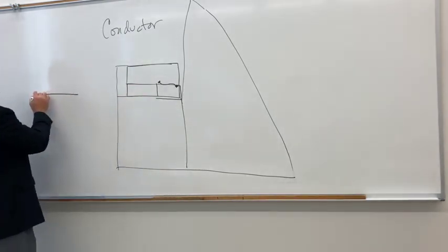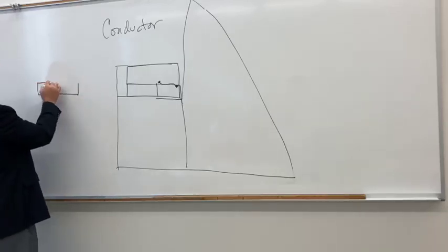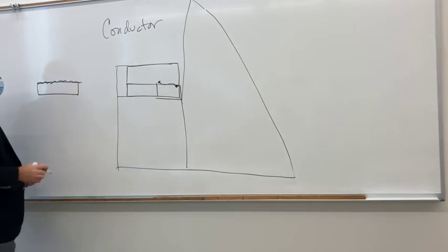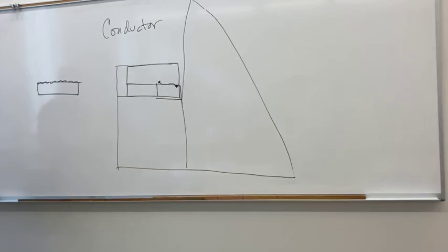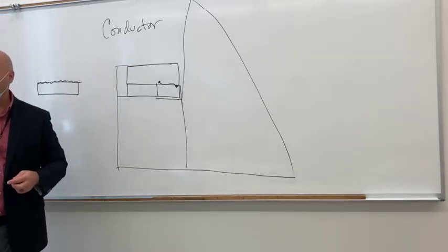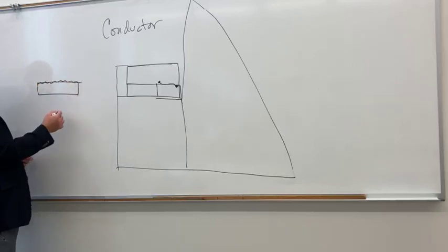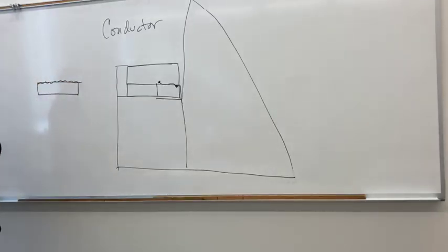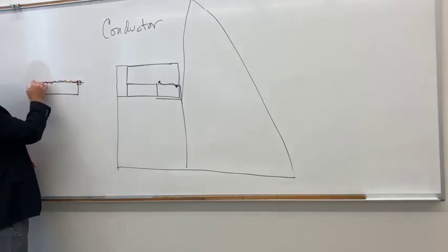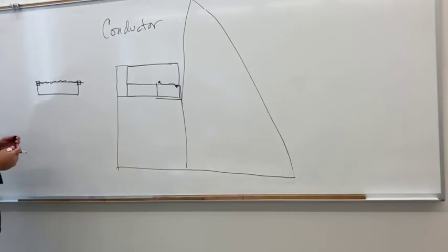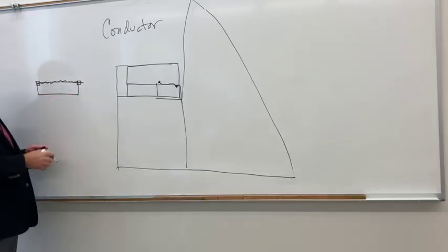So I've got patio, and I've got fence posts, and I've got electric fence wire. So we're going to say that's the wire. It's pulled tight. I've got these posts, but the posts have to be not touching another conductor. Okay? So you've got the wire, and it can't be touching anything that resembles a conductor. So what you've got are these little plastic things that the wire goes through. The plastic things keep it away from the fence posts. Okay? So the fence posts would be a conductor, but with the little plastic thing on it, it prevents the wire from touching a different conductor.